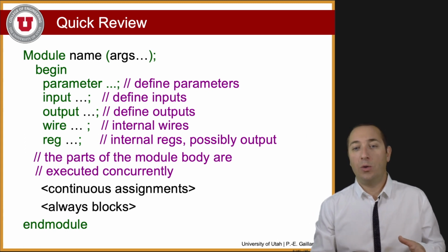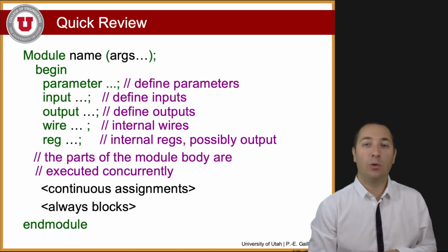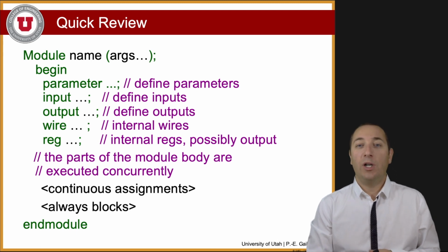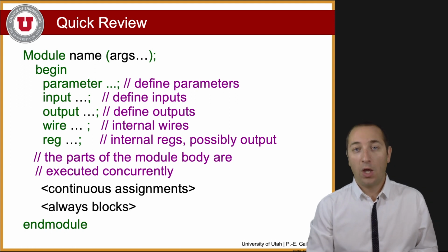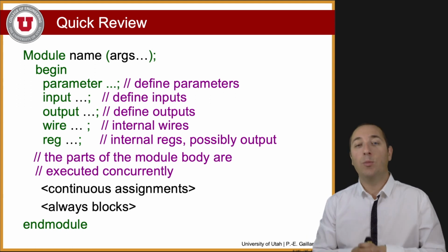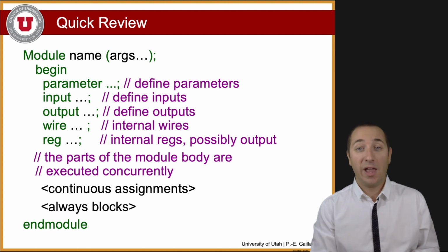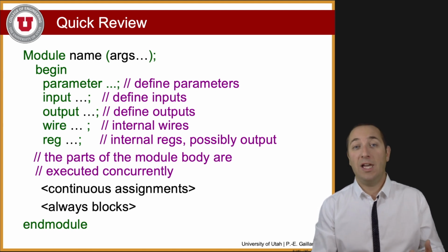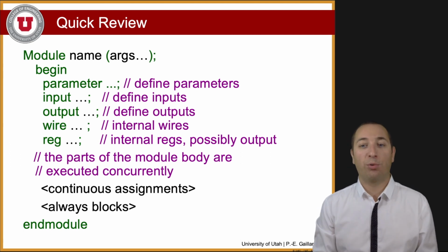I'd like already now to mention that, as you already know since you are familiar with Verilog, Verilog should not be used to write a piece of code as a software designer would do. You're using Verilog to describe a hardware element. And as such, you need to know what your circuit is supposed to do, you need to have a block diagram written, and you need to understand that all your various blocks are going to work and be evaluated concurrently. It is not sequential as a regular C program would be.